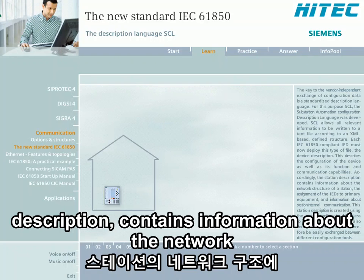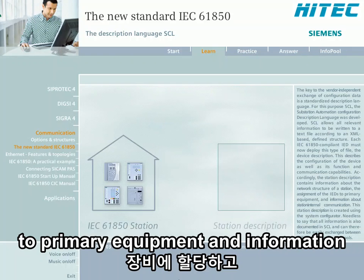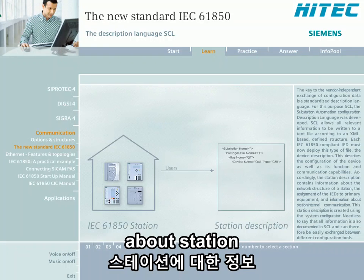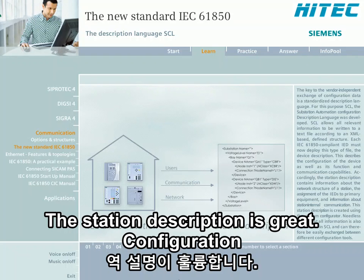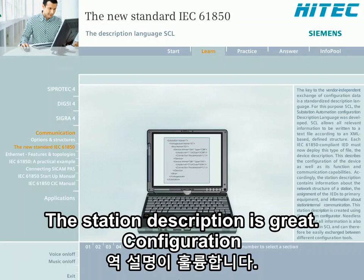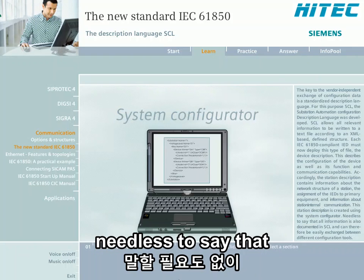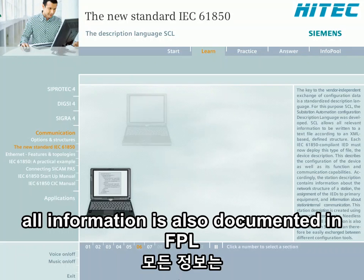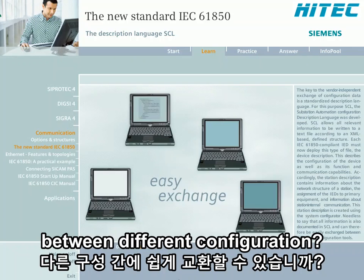Accordingly, the station description contains information about the network structure of a station, the assignment of the IEDs to primary equipment, and information about station internal communication. The station description is created using configuration software, the so-called system configurator. Needless to say that all information is also documented in SCL and can therefore be easily exchanged between different configuration tools.